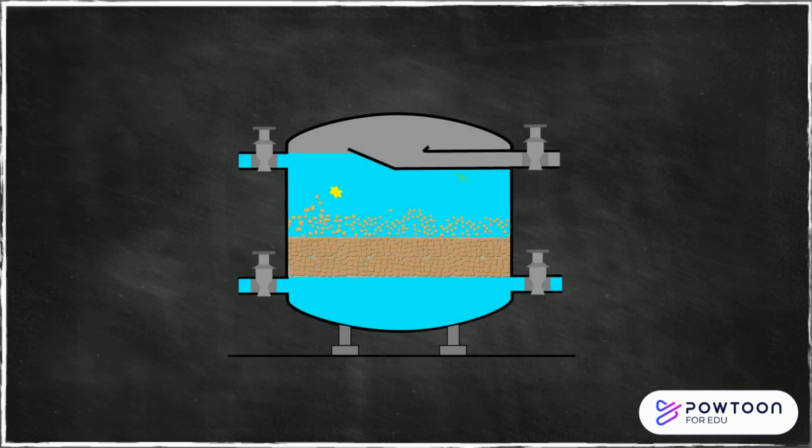Water using gravity is pushed through the filtration media, and as water passes through the sand and gravel, fine solids are removed. As the filter media catches and sorts out the fine solids, it holds less and less water. Therefore, the pressure must keep increasing to push water through the sand.